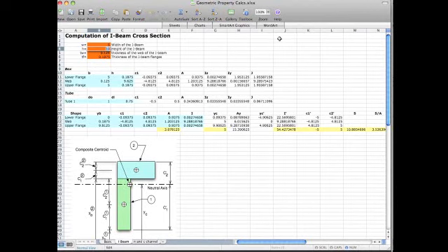All right, so now you have a, I probably should make a new picture here, but I'm a little too lazy to do that. But this will actually give me a way of computing I-beam sections. If I change the width to 6, you can then see the effect. And the nice thing about this is I can actually change these variables and try to come up with a good effective S over A or something like that, all right?